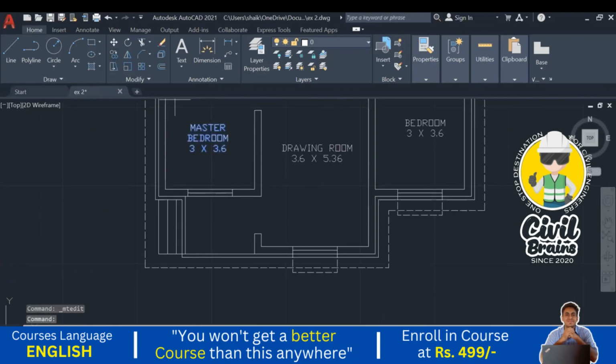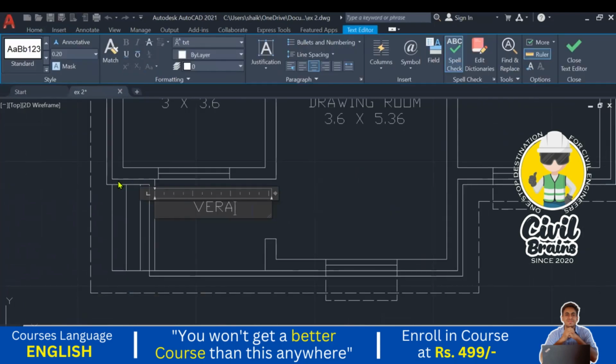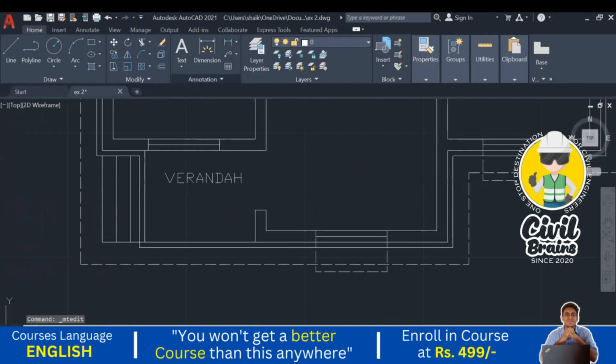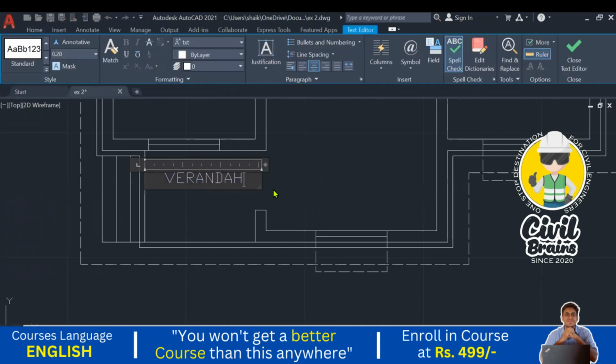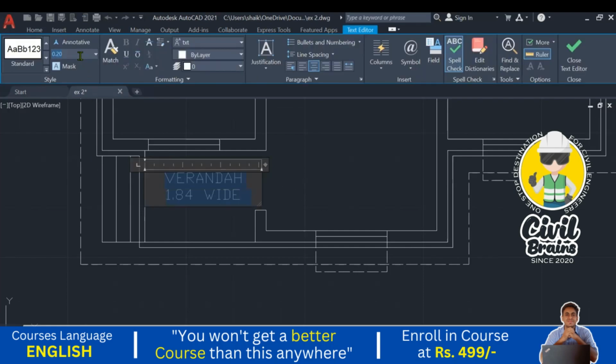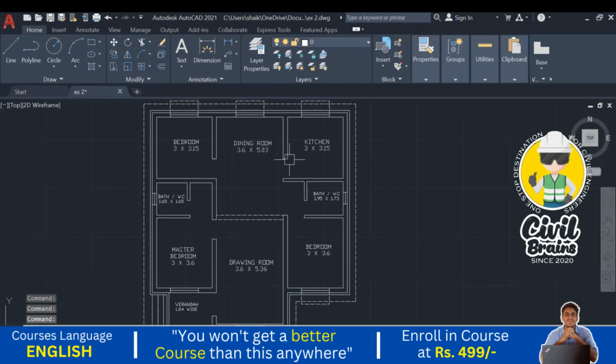Left is veranda. So I just write it here. Veranda. How much is the veranda? I just check. I just click here. 1.84 wide. I just want to size. I just reduce 0.15, so that you just adjust that one where it will look good.